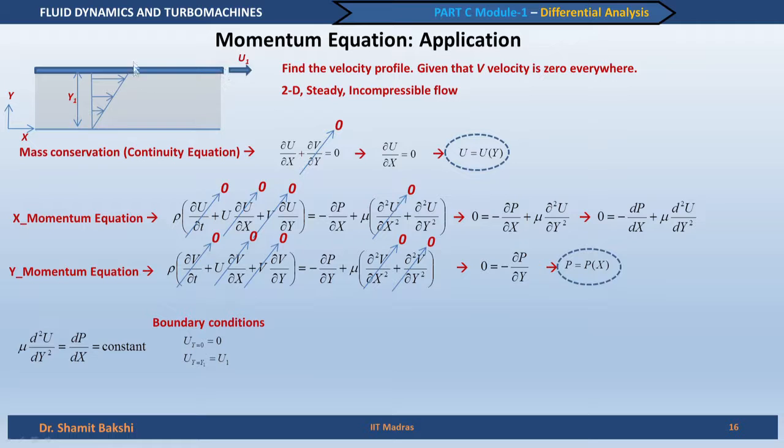So, at both ends we apply the no slip condition, that means there is no slip between the fluid and the solid object with which it is in contact. By applying that condition, we can easily integrate this equation, it will come in this form. If you just do this integration, this is basically the double derivative of a function being constant, which in this particular case is given as dp/dx.